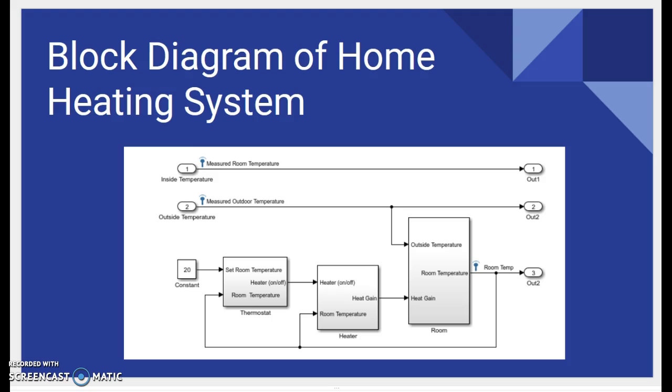In order to mathematically model a home heating system, it is helpful to first create a block diagram. The block diagram is made up from the components or subsystems within the heating system. The first step in building the diagram is identifying the components. In this case, we will be working with a heater, a thermostat, the house, modeled as one room for simplification, the outside environment, and the inside environment.